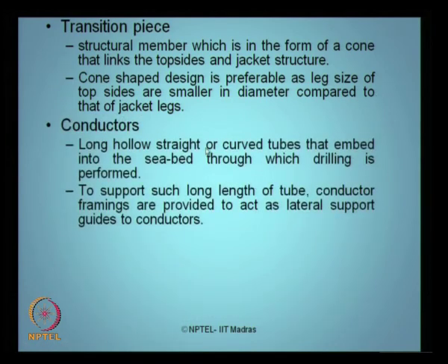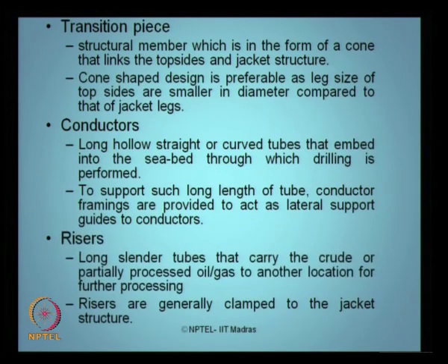Conductors are long, hollow, straight or curved tubes that embed into the seabed, through which drilling is performed. To support such a long length of tube, conductor framings are provided. Risers are long slender tubes that carry crude oil or partially processed oil to another location for further processing. Risers are generally clamped to the jacket legs.